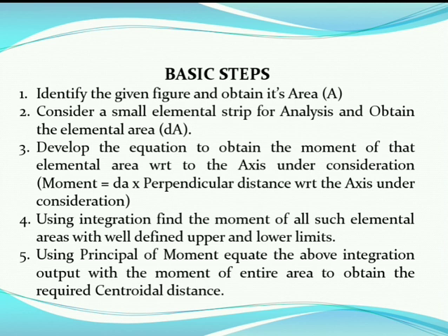In the fourth step, use integration to find the moment of all such elemental areas, because the entire figure or the entire area will be made up of a number of such small elemental areas. So to find the moment of all the areas, we use integration within the well-defined upper limit and lower limit.